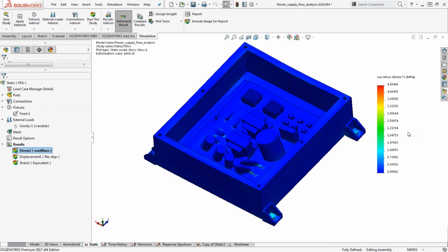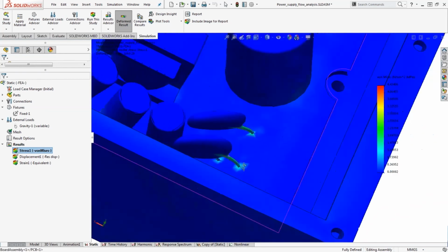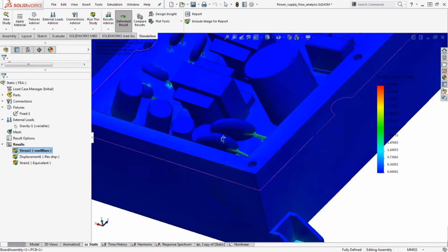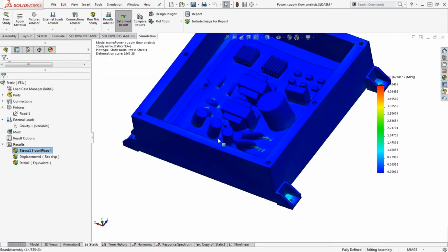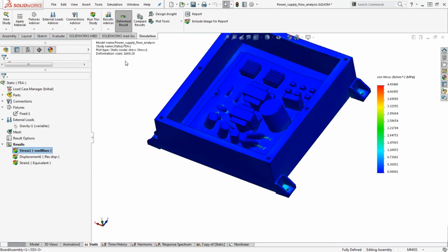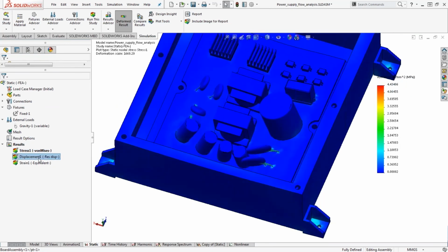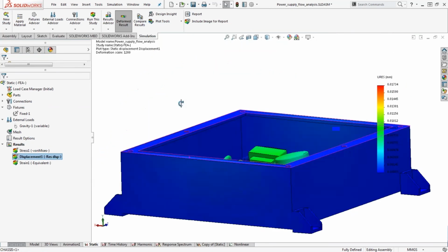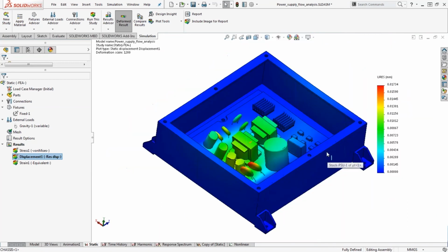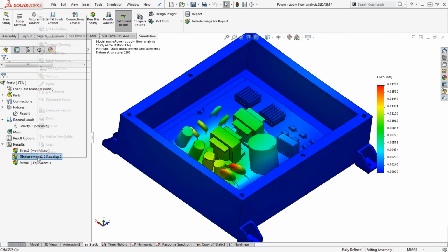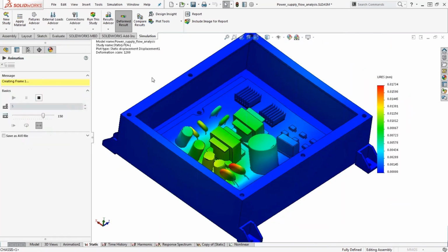You see that I have the option to define different directions of where this acceleration is going to be applied. So we could get some first level type of acceleration load onto this assembly and still get the results like stress and displacement, of course, if we're within the guidelines of what a linear static assumption offers. So after we mesh our model, we break down the model into these small elements here, and then we run the analysis, and we get something like stress.